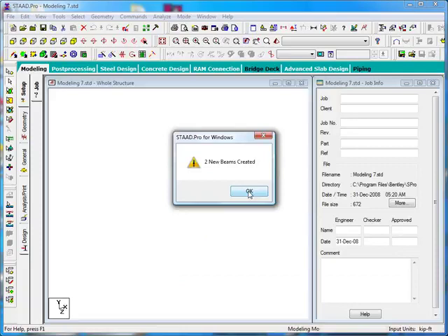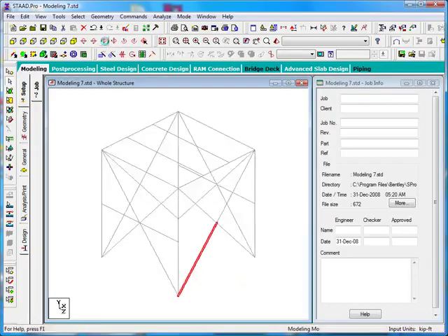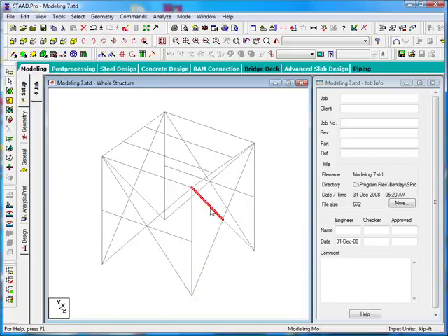So I'll click OK. And to really help visualize this, what I'll do now with the beams cursor is just click on individual elements in that front cross brace and show that they've definitely been broken at that common node. If I use the hotkey Shift and the letter K to turn on node points, we'll now be able to see that common node at the crossing point. Notice that nothing happened with the 2 braces that are in the rear of the structure.